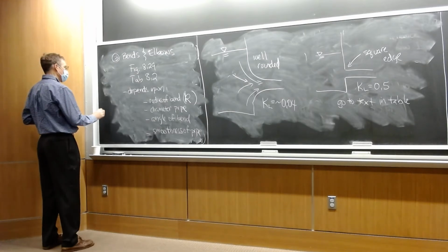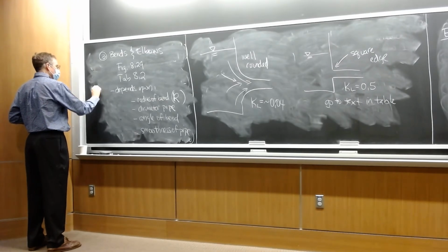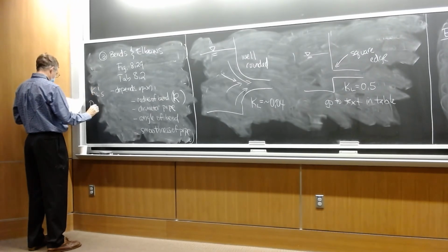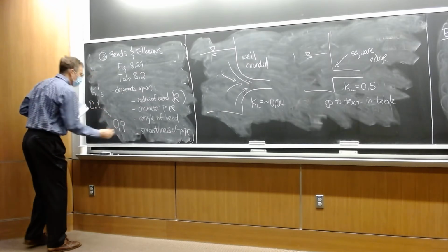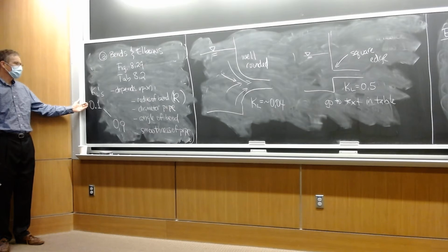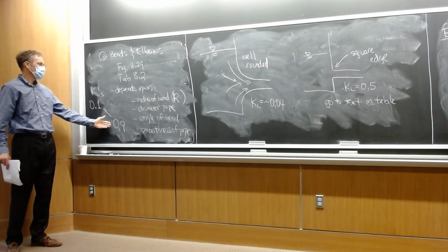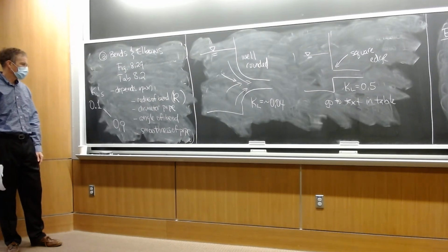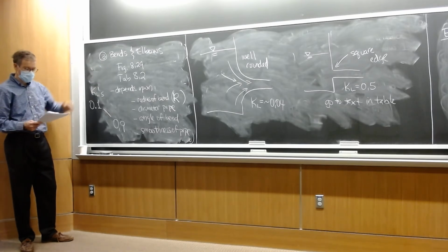Depending on what you come up with for all of those factors, you'll get a K of L that's down in the 0.1 range for smooth pipes, large radius bends and low angles, all the way up to tight radius, rough pipes in small diameters. So you would go to those tables to look it up.